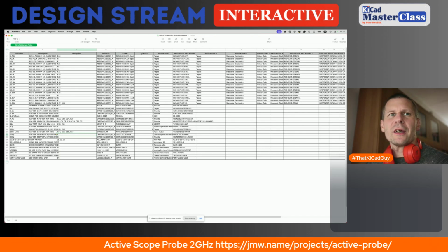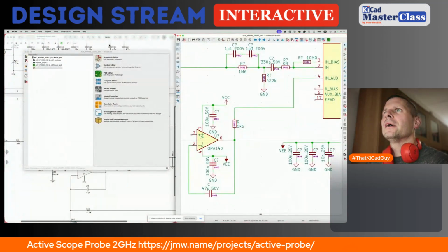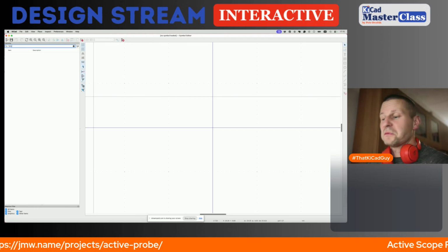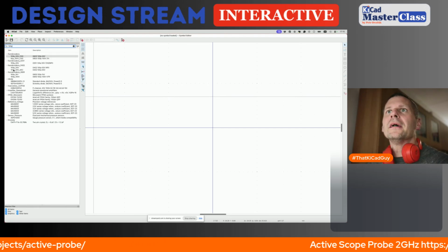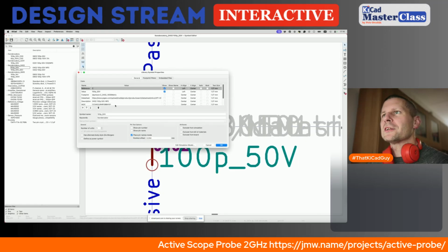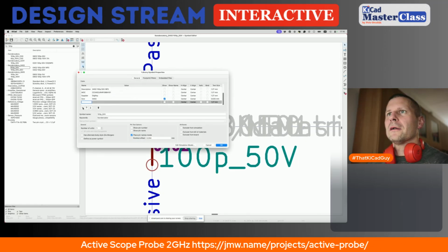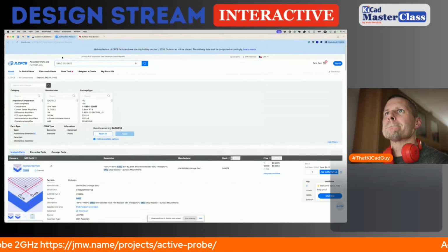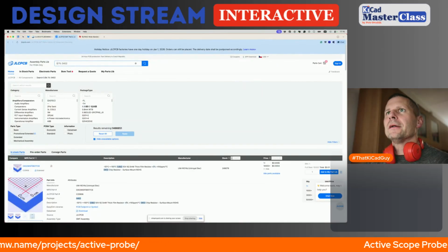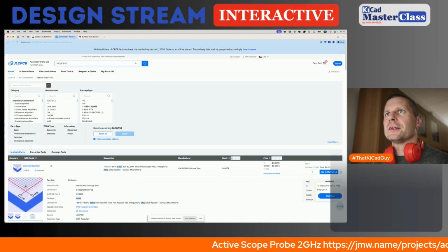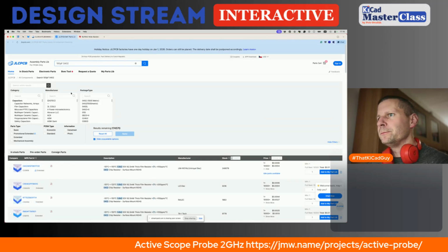So let's check my database again. 100 picofarads should be there. Yes, it is here. I have to check the JLC PCB code. Not present, so I need to edit. 100 picofarads, no percentage, 0402.